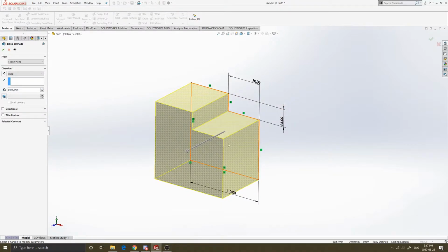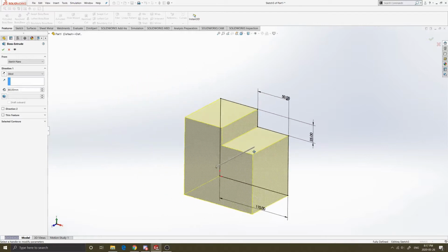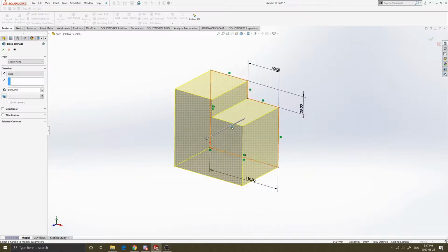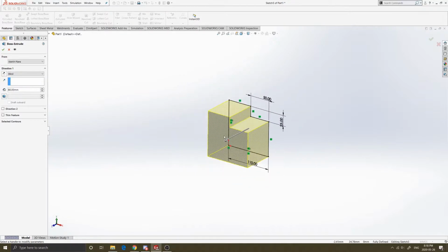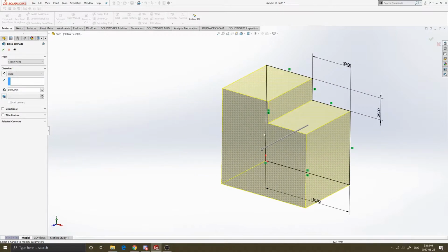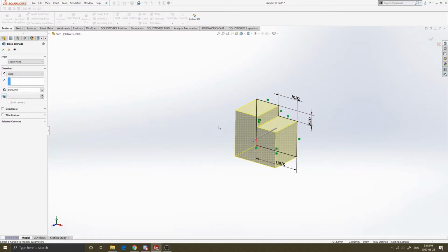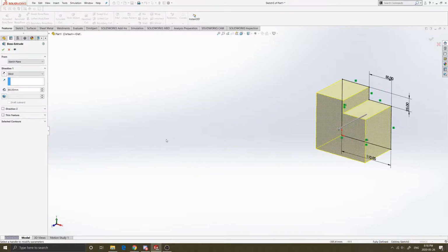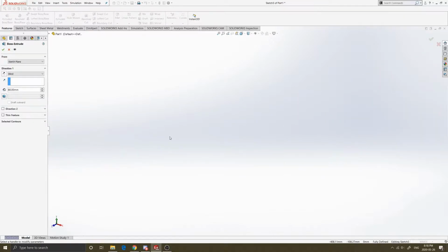And a nice way to control how your image looks in SolidWorks is by using the control key and your mouse button. If you use the scroll button, this lets you zoom in and out. When you zoom, it will always zoom in where your mouse is at that moment. So as you can see, if I zoom in, it zooms in on this point.